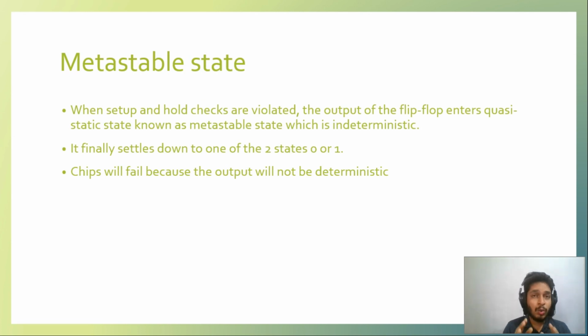So in order to avoid this, we must ensure that the setup and hold checks are always proper, and that the timing is clean, and setup and hold timings are always met in the design, so we will never end up in the metastable state.